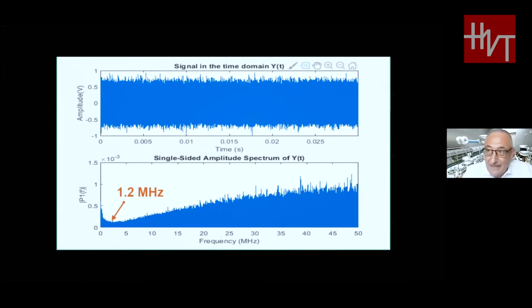For that reason, with other technologies you have to look for the noise level, and the best way is to place the sensor close to the realistic or real position on the conductor, but it's an approximation. And of course, the question is also related to what is the best bandwidth to measure. To measure partial discharge with this kind of noise, what is the frequency where the noise energy is the lowest?